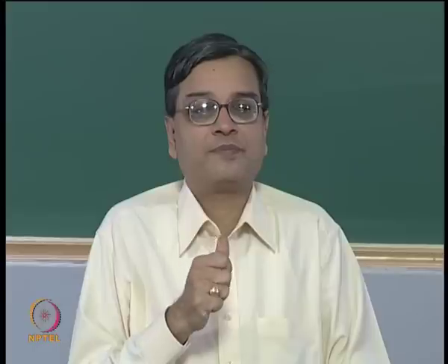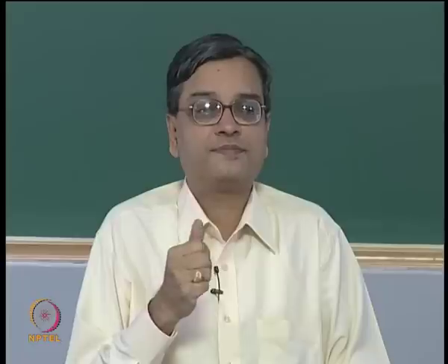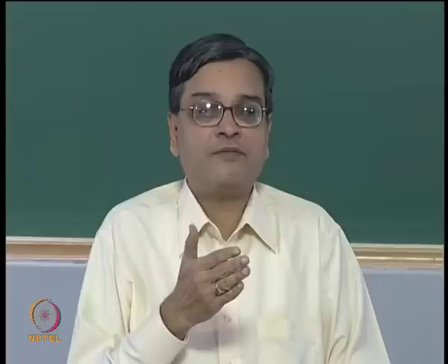And in this class what we had looked at was, we have evaluated the stress intensity factor by using the stress function definition, and then we proceeded to find the stress intensity factor for triangular loading on the crack faces. We said another important problem is, if I have a constant pressure on the crack faces, which is an equally important practical problem, we found the stress intensity factor as P naught root pi a.